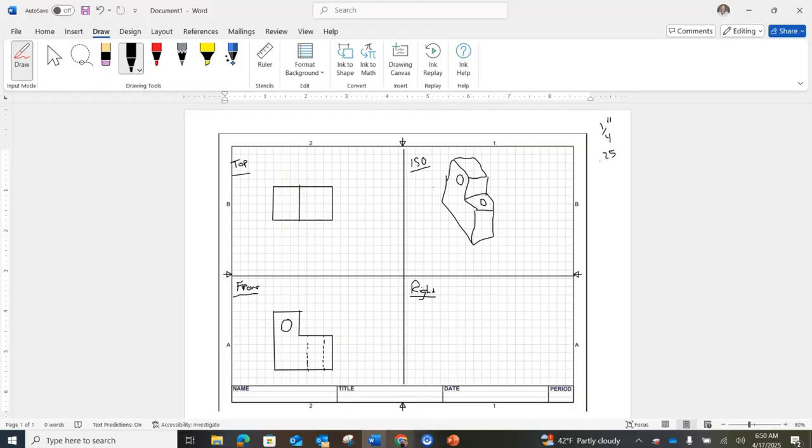So if you remember back to that PowerPoint talking about the alphabet of lines, if we can see it, it's an object line. Okay? Because my circle is 1 square deep, a circle that is looked at in two dimensions, or in an orthographic view, a cylinder becomes a rectangle, right? So I can just make my dotted lines there. And then this one's too wide, so I can actually draw this hole 2 squares wide. See how everything's lined up and adjacent, and even the hidden lines are lined up with this.